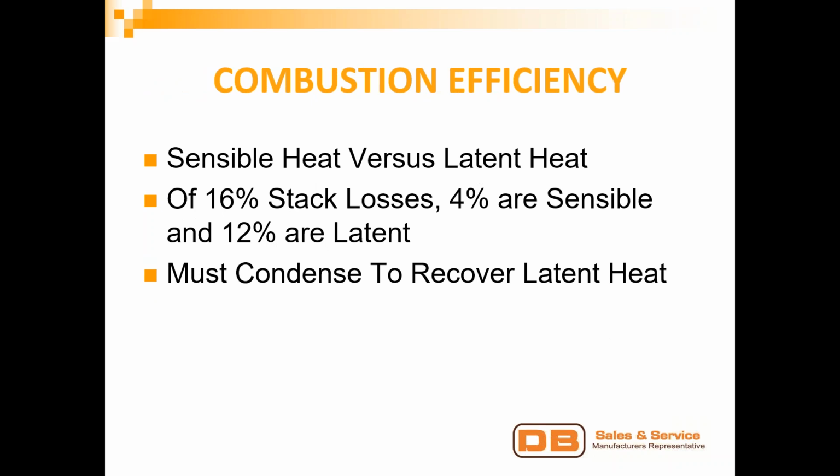Combustion efficiency, we have sensible heat versus latent heat. So if you have typical stack losses, if you have an 84% efficient boiler, your stack losses are 16%. Of that, 4% are sensible and 12% are latent heat. What is latent? That is basically the heat used to change water that is created during the combustion process into water vapor.